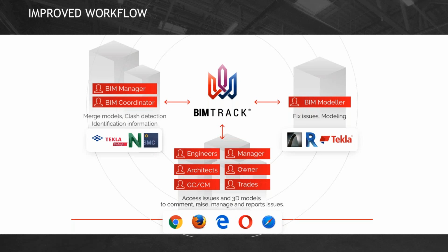So the workflow today, an improved workflow, is that within, again, using the BIM manager or VDC coordinator with Navisworks, they can convert their viewpoints to issues or convert their clash detection reports to issues and let BIM Track manage that process. BIM Track will send an email notification to the recipient saying, you've received these items, they're due on this date. It's very clear what they need to work on. In fact, BIM Track will actually send a friendly reminder the day before that issue is due, saying, hey, you've got 20 items that are due before tomorrow's coordination meeting. You might want to get those done. So, instead of the BIM manager having to herd cats and the team to get things done, BIM Track plays an assistant role in that.